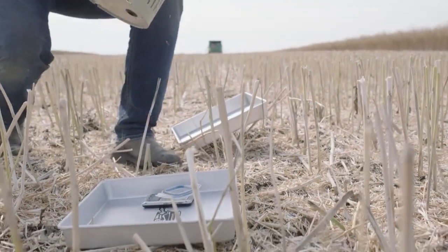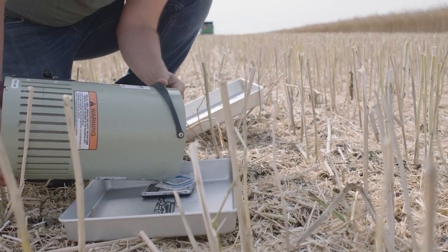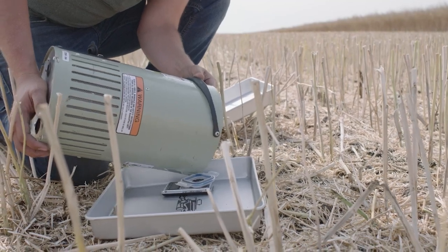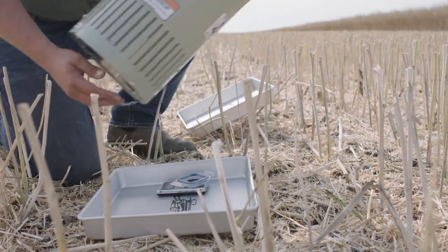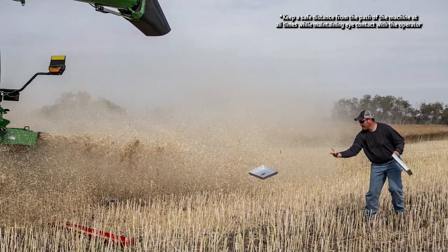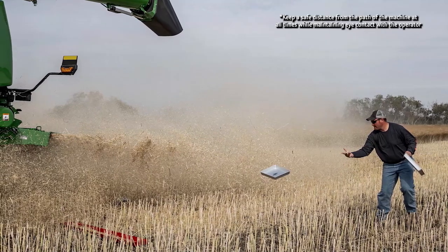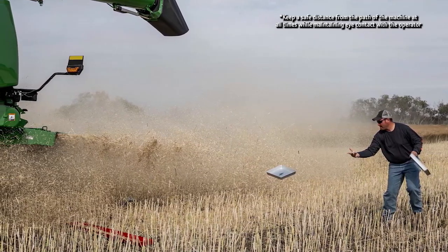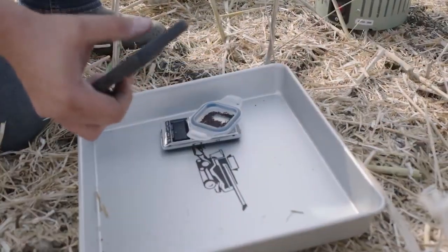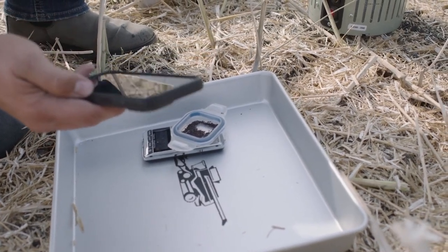Now is the time to ground truth the already harvested ground behind the combine to supply these results into the system. There are various methods, such as lightly scratching away the residue from a 1 foot by 1 foot square to count grain inside this area, but it is highly recommended to utilize loss pans and throwing them between the front and rear axle, under the center of the combine. It is best practice to also get one of the left and right of center to get a reliable loss calculation. Once we have our pan full, we will need to clean out the trash until we are down to just our kernels of our respective crop.